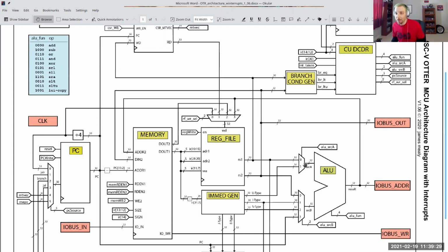And so we're not going to make that be a problem. We're just going to slow everything down so that you have plenty of time. And so that's why we put the divide by 2, right? So that maybe your decoder isn't as well designed as it could be. We add extra slack time in so that it still works, right? So that's why we put this in.